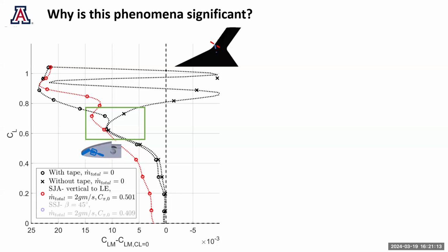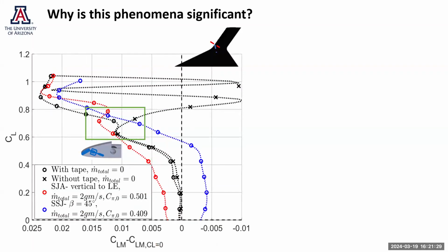So we get just the pitch up behavior, with the zigzag pattern that was earlier there for the black circle, but at a different alpha angle. And at that same location, if we introduce a steady supersonic jet, designed for Mach 1.5 but inclined towards the inboard part of the wing, we completely eliminate this zigzag behavior. So you see the blue curve doesn't have this zigzag behavior.